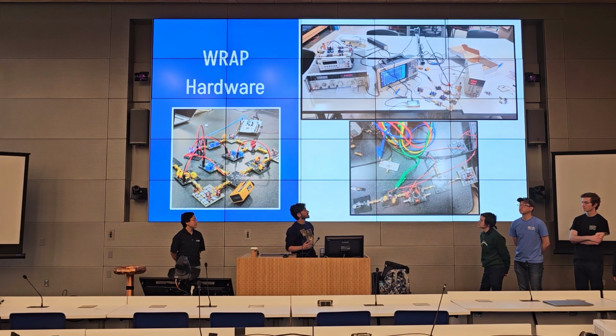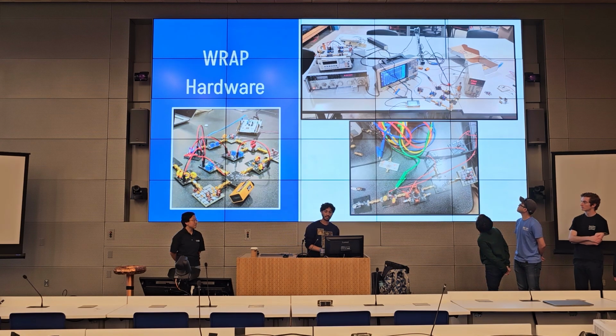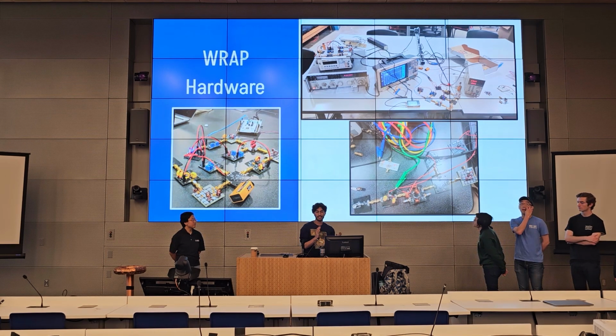That's one of the tools we'll use. And over there in the bottom corner, we have a NanoVNA, and that basically tells network parameters, so stuff like impedances, reflections, gain, etc. And the spectrum analyzer is for frequency measurements, because at the end of the day, we want to verify, hey, we get a signal out at 27 megahertz. So those are two tools that we use. We also use oscilloscopes quite often, and over there, the big thing on the left is a signal generator.